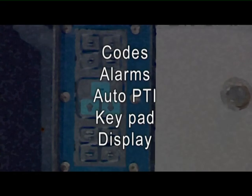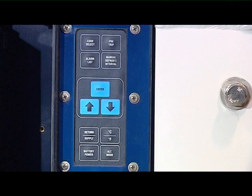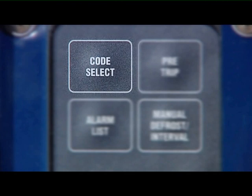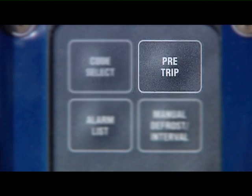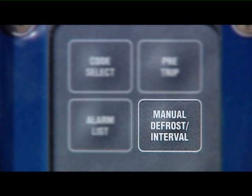Controller function codes, alarms, auto PTI, keypad and display. Keypad. The keypad consists of 11 buttons which allow the user to get information from the controller. The code select key gives access to the function codes. The pre-trip key displays the pre-trip selection menu. The alarm list key displays the alarm list and clears the alarm queue. The manual defrost interval key displays the selected defrost mode.